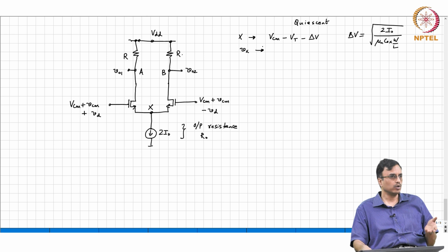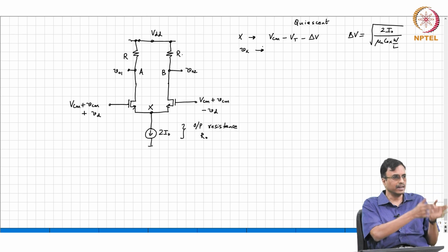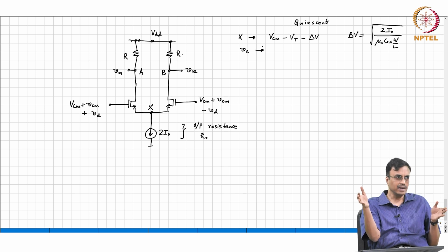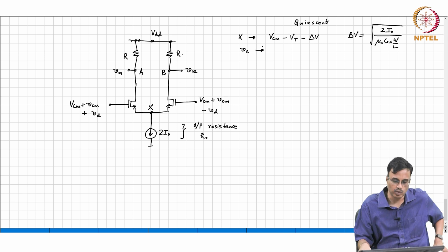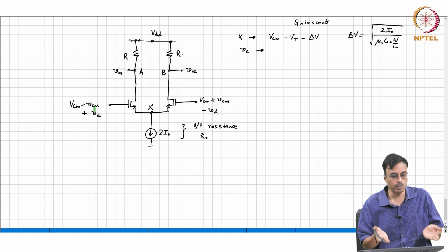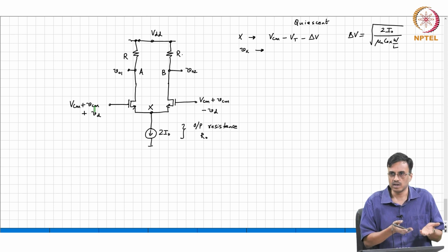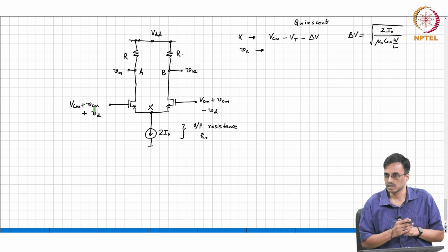So, what do we do? Well, again we go back to symmetry, we find the individual voltages, and when you put both of them together, you can think of this as the following. If you want to analyze what happens when there is a common mode change as well as a differential mode change, simply by superposition you can consider only the common mode first, only the differential mode next, and use superposition to add up the potentials that you get in both half circuits.